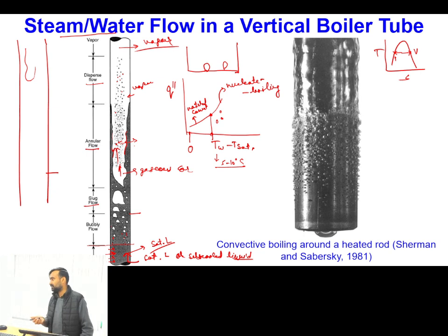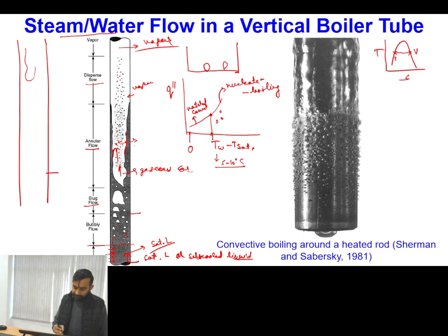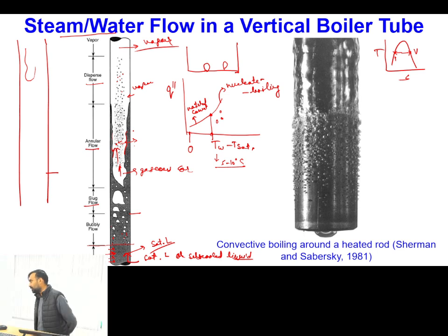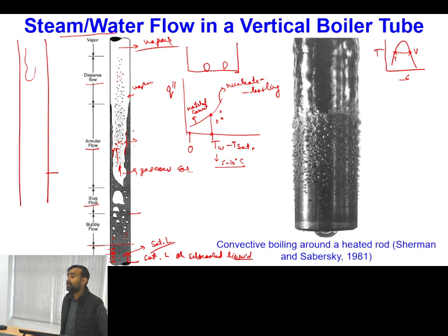So that is the reason that in a phase change heat transfer pipeline, there can be significant variations at different portions in the volume fraction of liquid and vapor, and these variations significantly change the distribution of the phases.